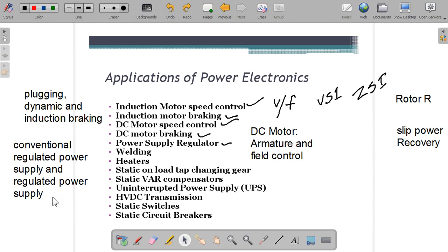Here, AC supply is directly given to the rectifier without a transformer. The DC output of the rectifier is the input to the high frequency inverter. The output of the inverter is stepped down to a lower voltage AC with the help of a transformer. Now this high frequency low voltage is rectified with the help of a rectifier and filtered using L and C components. As the frequency of the transformer is high, from the basic EMF equation, the flux required gets reduced. Thus the transformer size gets reduced.